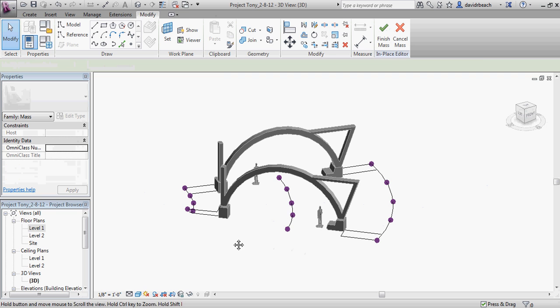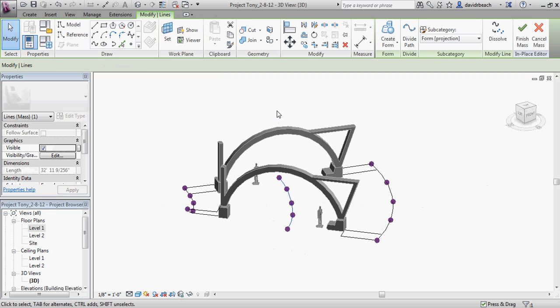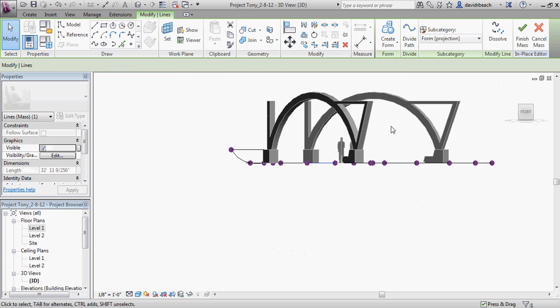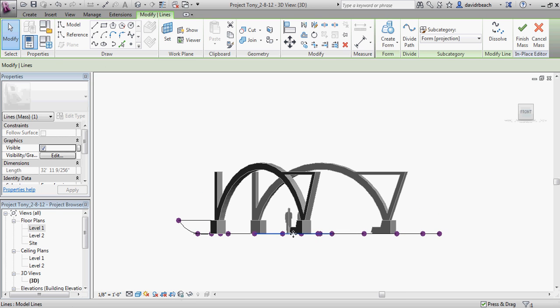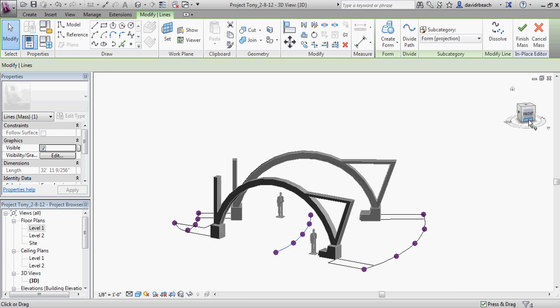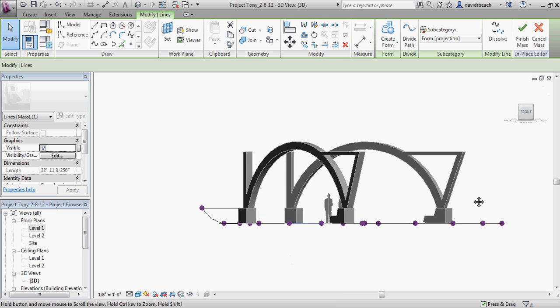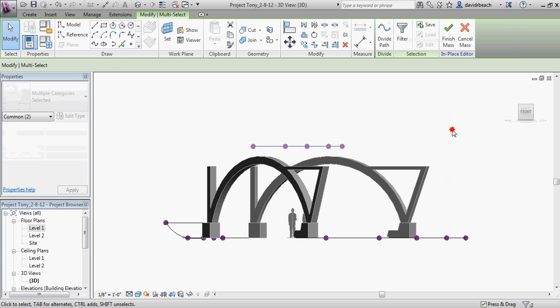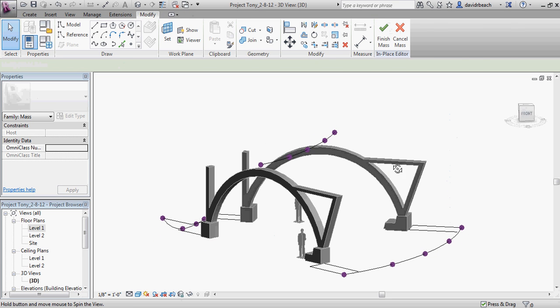Now, what I want to do is move these guys up so that they're happening above the trusses. So I can stay in my 3D view typically and do this pretty easily. I'm going to start with this middle guy. I'm going to move to a front elevation view on my view cube. That's going to lock me moving on the z-axis. So I'm going to move this centerpiece up 18 feet. So I have that happening there.